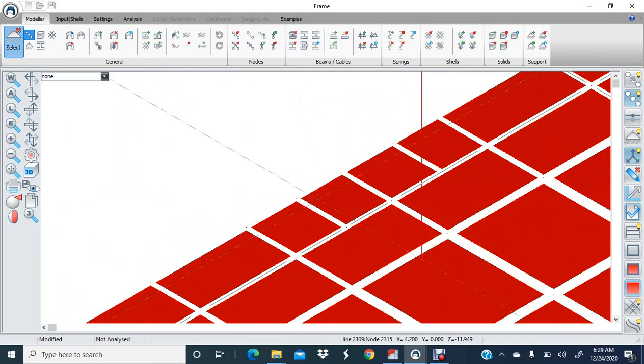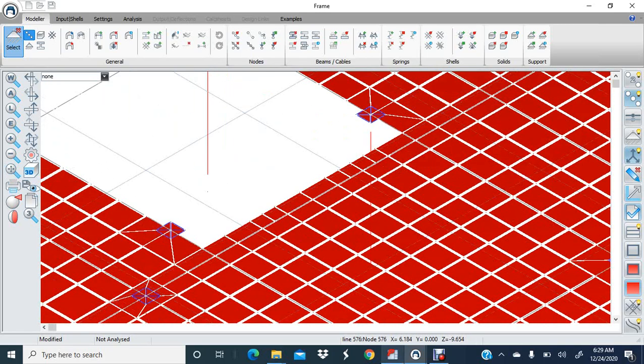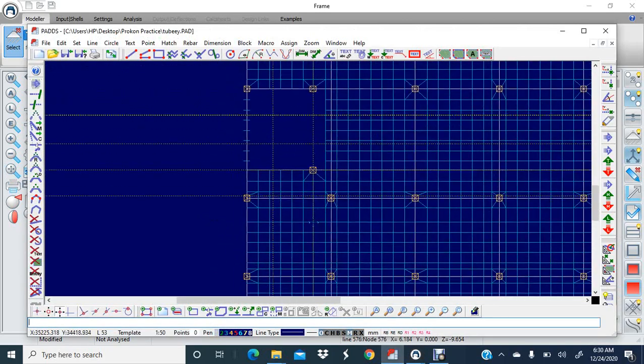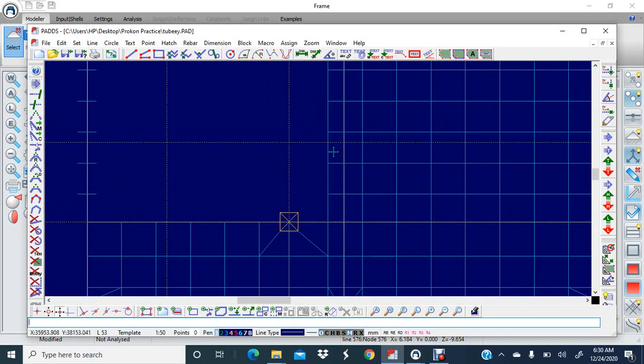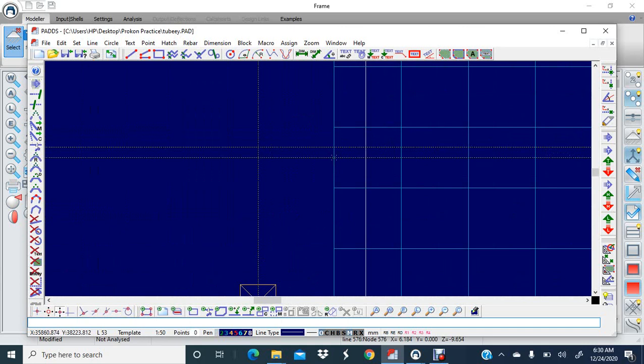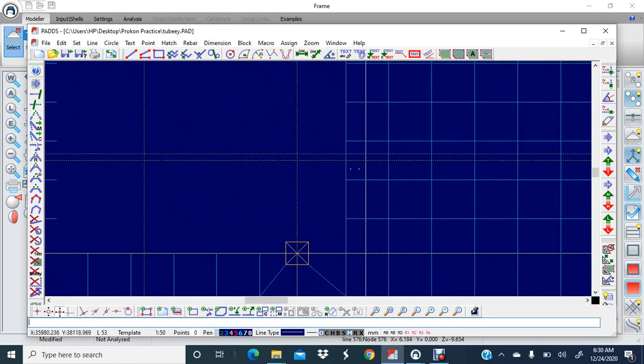It connects here. So let's check this lower one. The edge of the staircase is coming to that point. So insert LX, check this D2, that's 85.366 millimeter. Yeah. So we are moving this point up to there. So 85.3.